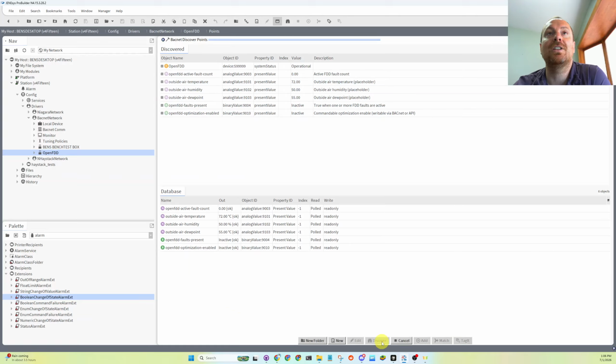If it's doing this, like I'm clicking this button, discover, discover, discover, discover, if we were doing that on a live building automation system, we'd be causing tons of bad global traffic. I wish you guys could see my other screen, because Workbench pops up these messages that a discover has gone, boom, boom, boom. It creates tons of traffic, and we want to be careful that the application is not pounding the BAS in any way, the live HVAC system.